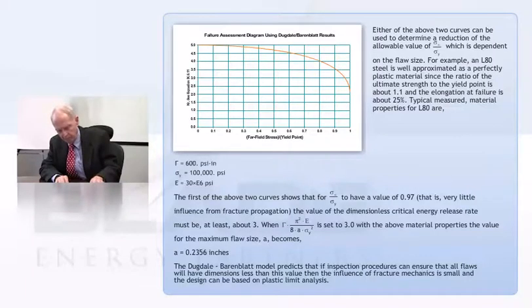If I do that and then turn this around and solve for the crack length, I get about 1/4 of an inch. So that's the kind of stuff that you're looking at, cracks on the order of that length. Awfully hard to find those cracks.